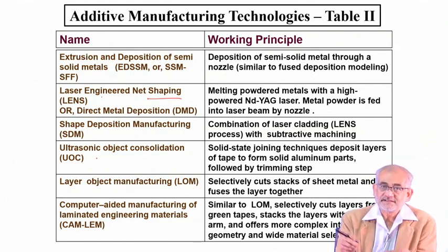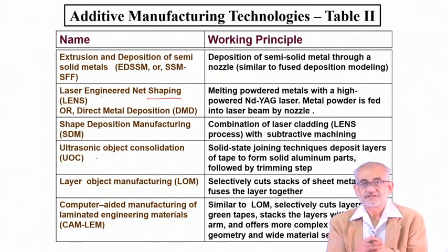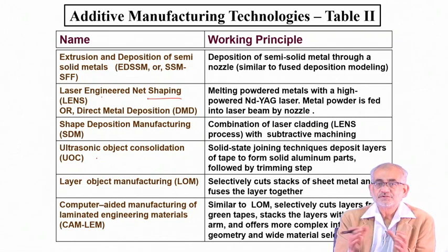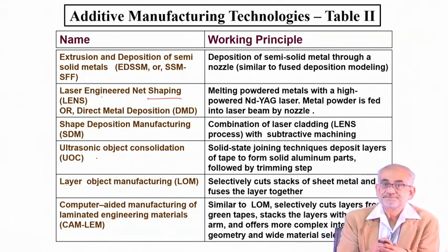And by controlling the laser and its power, you actually can make it melt, you can make it clad or deposit, and make it a very firm and dense structure. You can even create a lot of gradation in terms of thickness, shape, porosity, or other physical or chemical parameters. So the possibility is literally infinite. You actually can do complete engineering of finished component development and manufacturing using a single tool of laser with a powder feeder or a wire feed or some other material feeding system.